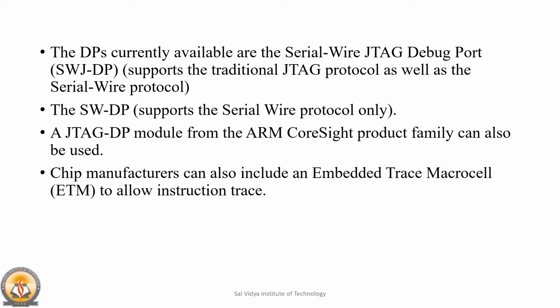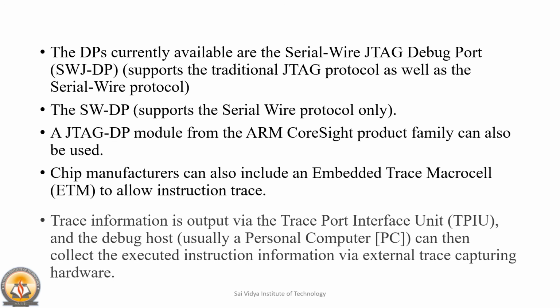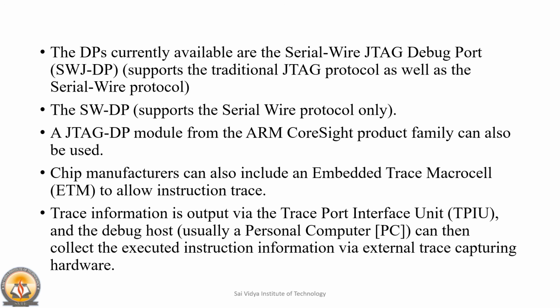The chip manufacturers can also include an Embedded Trace Macrocell, ETM, to allow instruction trace. The trace information is output via the Trace Port Interface Unit, or the TPIU, and the debug host, usually the personal computer, can then collect the executed instruction information via the external trace capturing hardware.